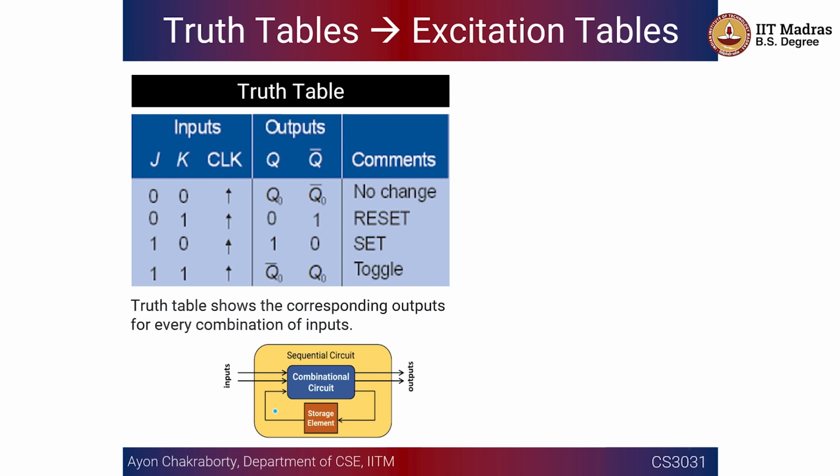So if it is a 3-bit counter circuit, it counts from 000, which is decimal 0, to 111, which is decimal 7, right? And you can see the count goes from 0 to 1, 2, 3, 4, 5, 6, 7, and from 7 it is again going to round up to 0, then 1, 2, 3, 4, 5, 6, 7, and so on.